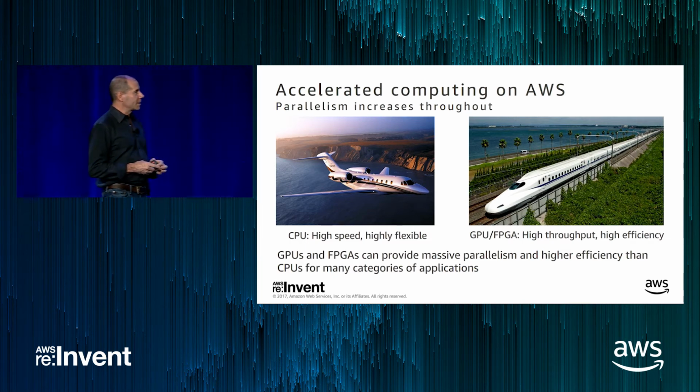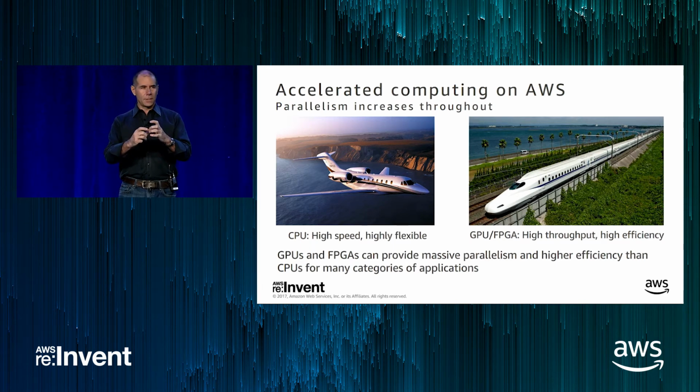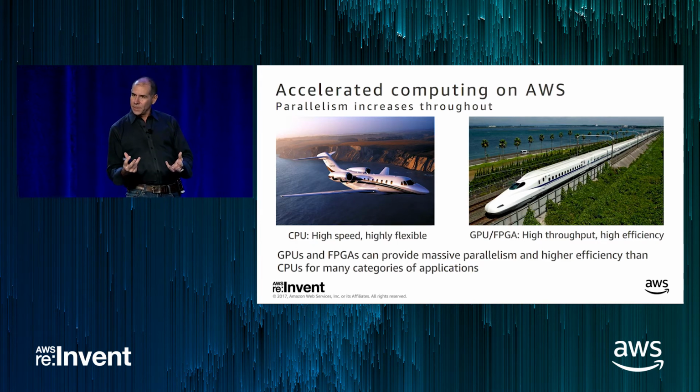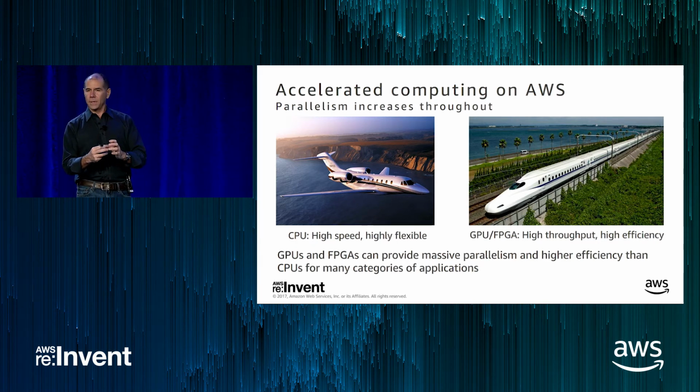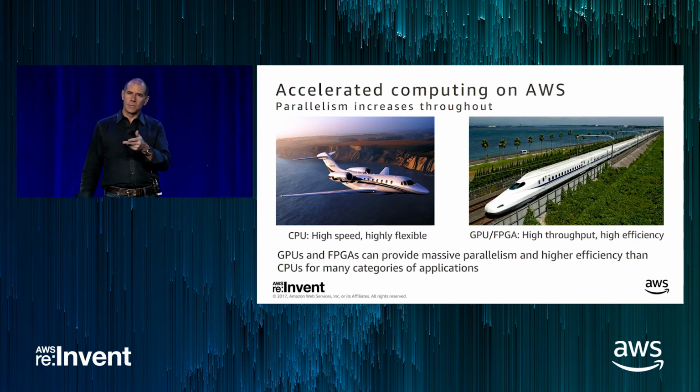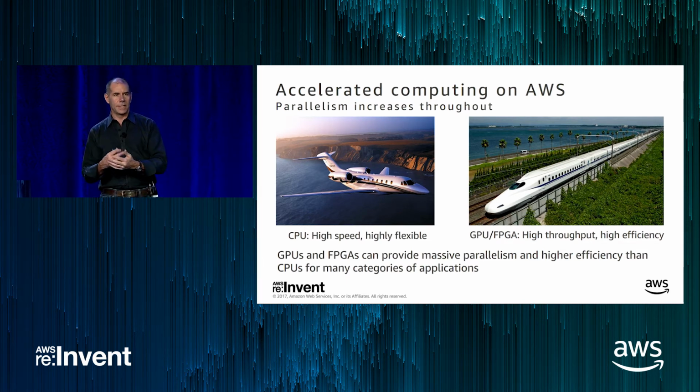The best way to think about accelerated computing is a metaphor. If you think about a legacy CPU architecture, Intel Xeon, for example, or really any CPU, it's a limited number of CPU cores on a die. Each CPU core has a limited number of ALUs, arithmetic logic units. It's got cache architecture, it's got data paths and so forth. It's built to be general purpose, but under the hood, it's actually a fairly limited architecture in that it's only a specific number of data widths, like 32 and 64 bits, and a limited number of ALUs that you're trying to traffic cop and bring all the data into and process.